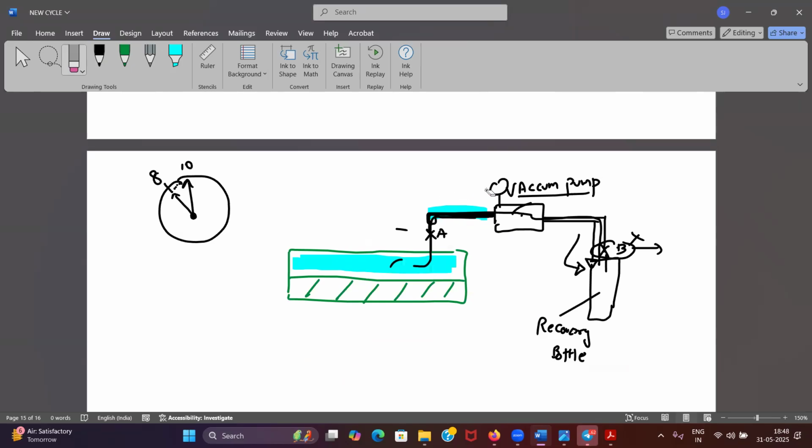Yes, sir. Okay, so will you be able to tell how to remove air in the system? And it will not be released in one time. You have to do it multiple times. Even if you come to 8 bar pressure, it will not release all the air in the system. Maybe some amount will still be remaining. Again, you have to do this process at least 3 to 4 times to remove all the air. Is it clear?